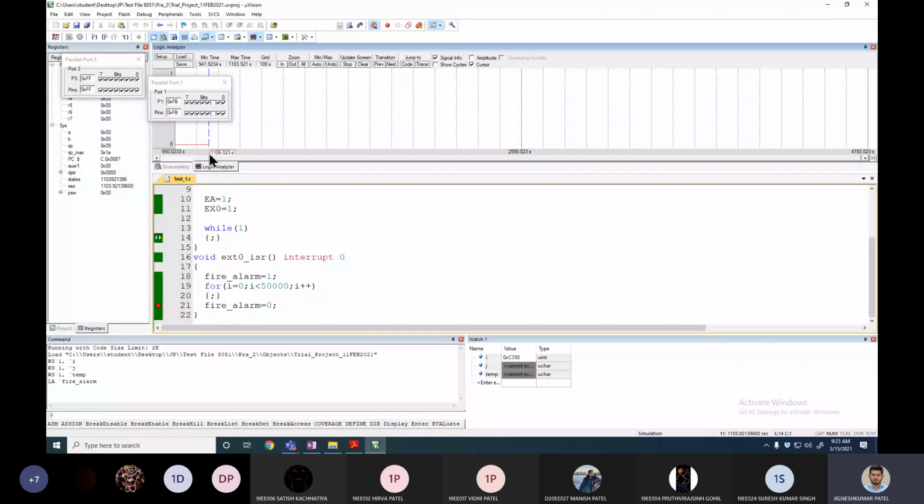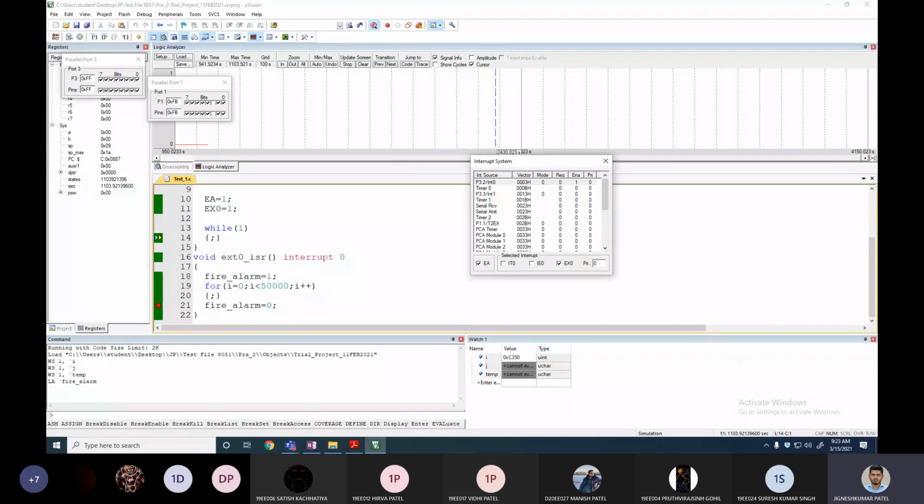Right now you can see your signal is 0. Why is it 0? Because no interrupt action is there. Now I'm going to generate an interrupt by getting this low. As soon as you get this low, you have this peripheral here and you can have your interrupts.